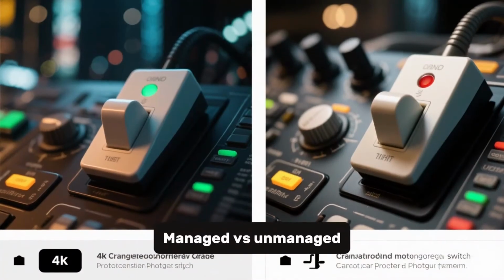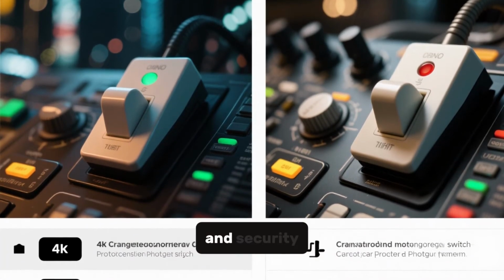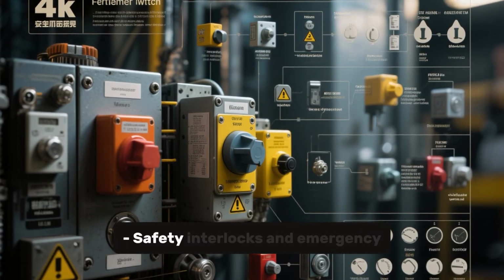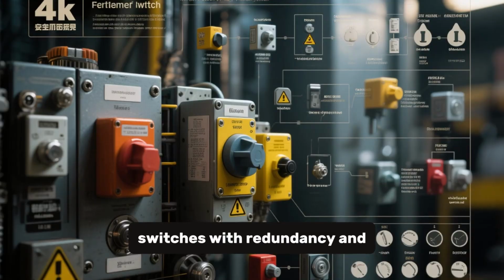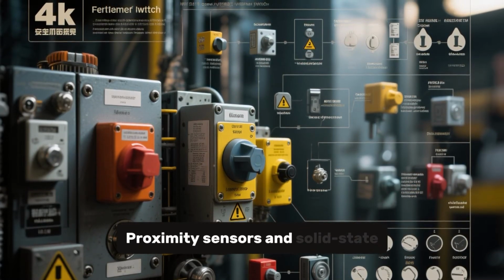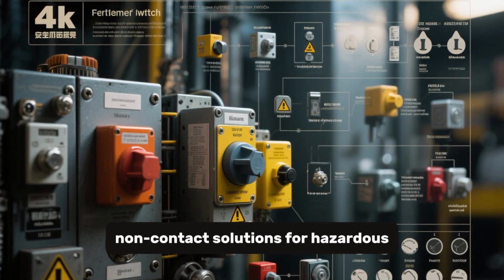Managed versus unmanaged. Managed switches support VLANs, QoS, monitoring, and security. Unmanaged are plug-and-play. Section 9. Specialized and safety switches: safety interlocks and emergency stops. Safety-rated switches with redundancy and force-guided contacts to meet standards such as ISO 13849. Proximity sensors and solid-state safety switches are non-contact solutions for hazardous environments.